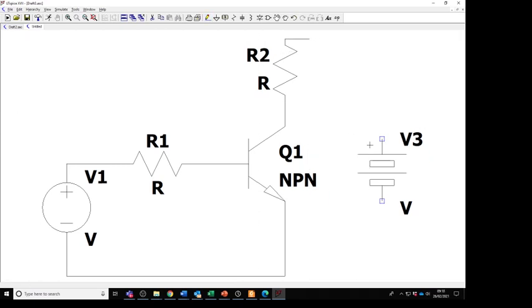So for more complicated circuits, we might want to just not join things up particularly. So what we can do is then label it with this one. So we can pick a label, and let's call it VCC, just for convenience, and then we can attach that to there, and then we can attach that to there. And now, even though there isn't a wire joining those two, because they're labelled the same, that makes it an implicit connection. So it just makes diagrams much easier to declutter.